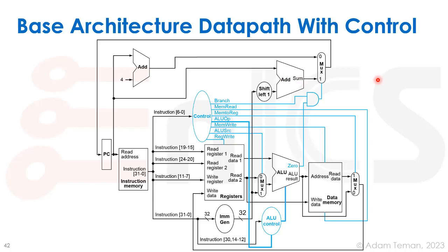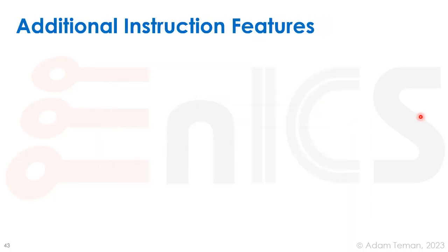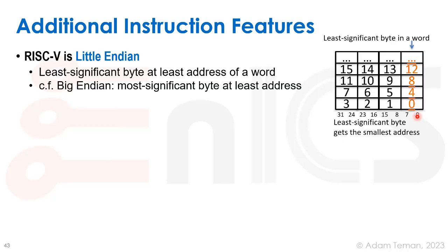Again, RISC-V is a specification of the architecture, and it doesn't go into the microarchitecture. And you can do this in many ways, but this is just one possibility, a simple possibility of breaking down how you take the base integer data path and turn it into a microarchitectural schematic block. So what other features can we talk about with RISC-V? First of all, that it's little endian.